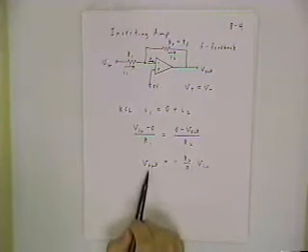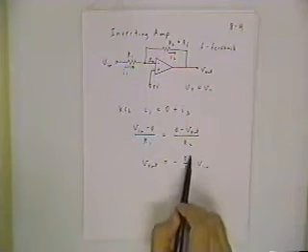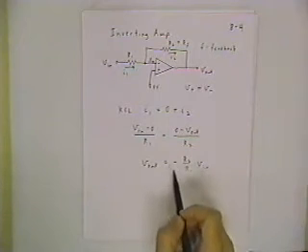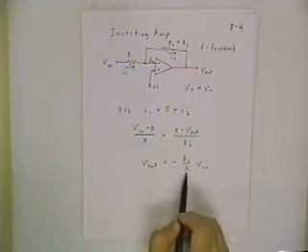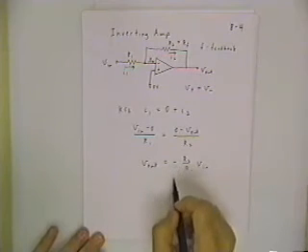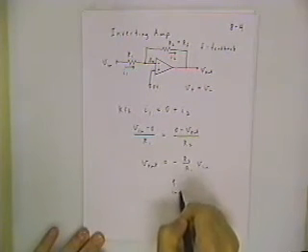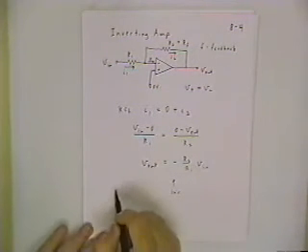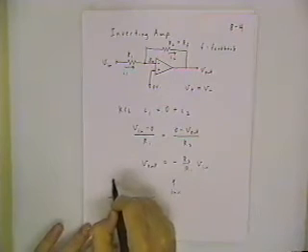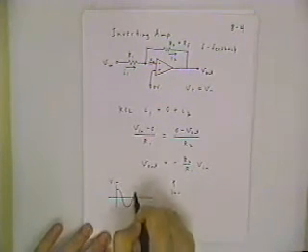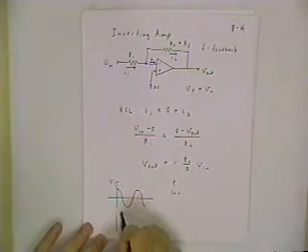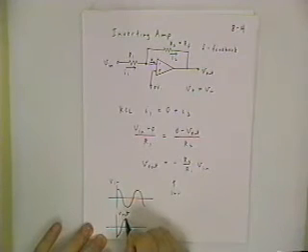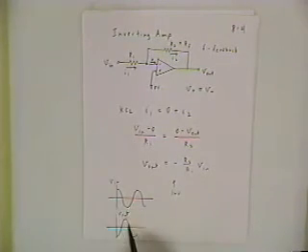What this says is that the output voltage is a multiple of the input voltage. That multiple can be positive, well, it's got to be negative. It can be larger than 1 or less than 1. It's always going to be negative because of this minus sign, and that's why it's called an inverting amplifier. For instance, if this were an AC input signal that looks like this, if Vn oscillates this way with respect to time, Vout is going to be inverted in phase, and so it starts off here and has its maximum where the other has its minimum, and so on.